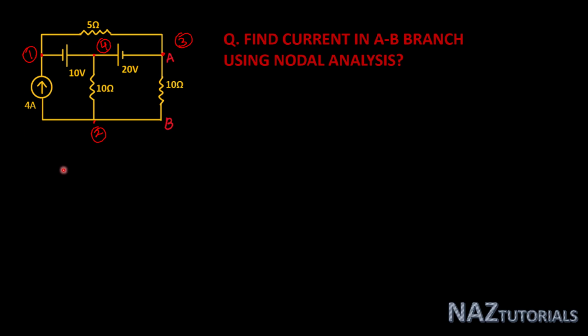If you select node 2 as the reference node, then node 1, node 4 and node 3 will be defined by some basic equations. If you select node 1 or node 3 as the reference, one node voltage will be defined and the other node voltage will be calculated in terms of the previous node.